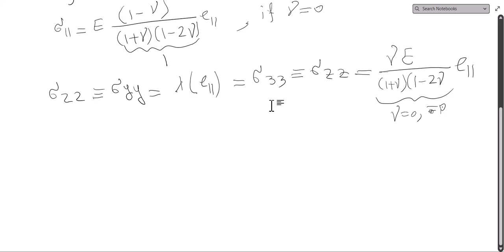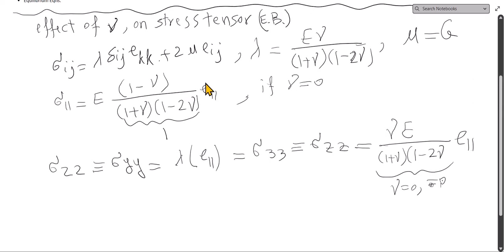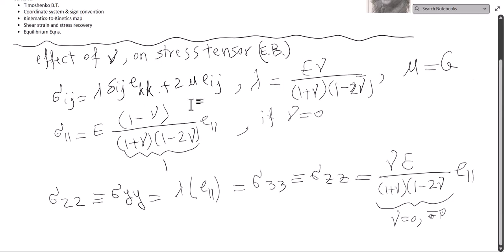So that's why we said that all these stress elements, which are the stresses on the normal y and normal z surfaces, in the y direction and z direction, can be ignored as compared to the main stress, which comes from sigma xx, the bending stress, and then we can continue with what we had.